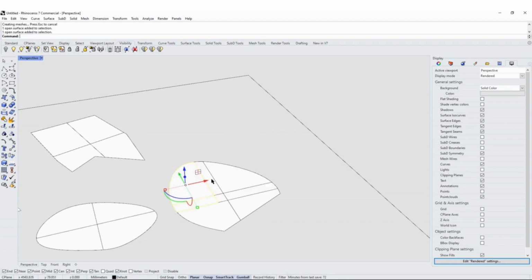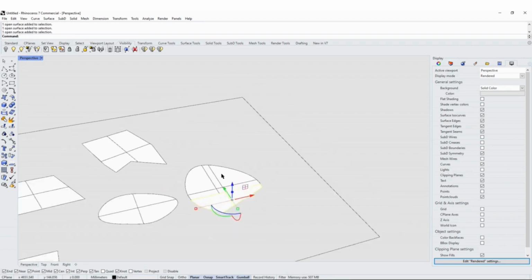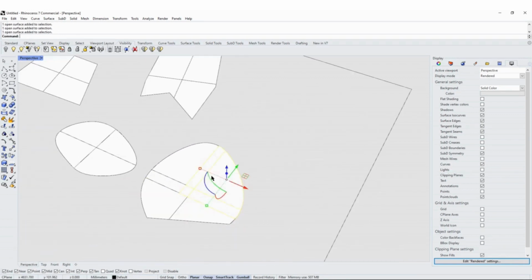So click and enter, two lines created. So now I have split this surface into different parts, but I would really like to connect them again because maybe I don't want them separated anymore. So of course you can always go with the option of join. As you can do join, and now this is one surface.